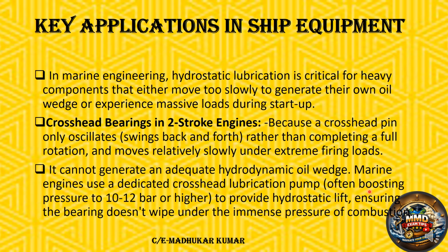Key application on ship equipment. Okay, so what are the key applications? Basically, we can see over here, the hydrostatic lubrication is critical for heavy components that either move too slowly to generate their own oil wedge or experience massive load during startup. So two major points are there when we talk about the ship's equipment. One is the speed of rotation, if the speed is less, and the other is the massive loads at the time of startup. So these two things are very important that we have to see.